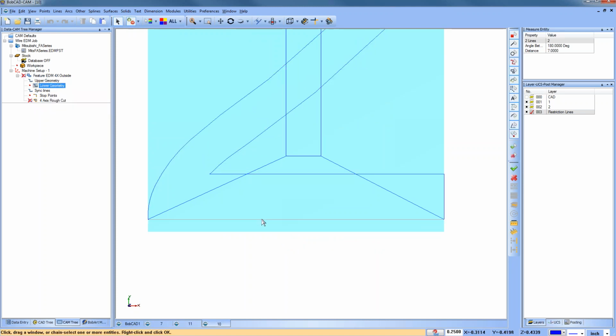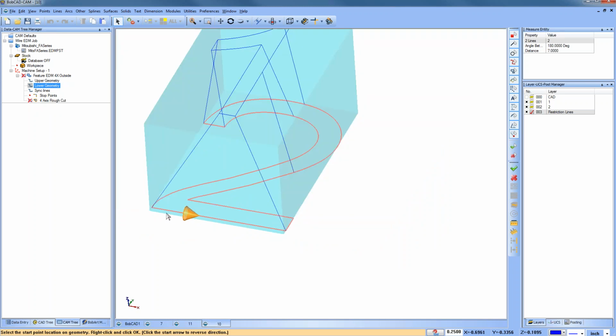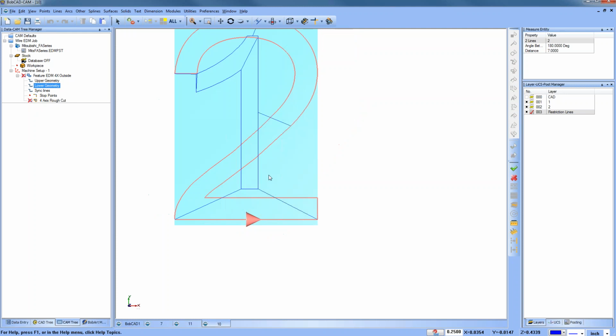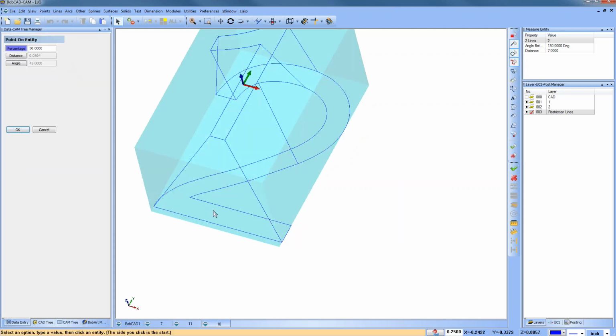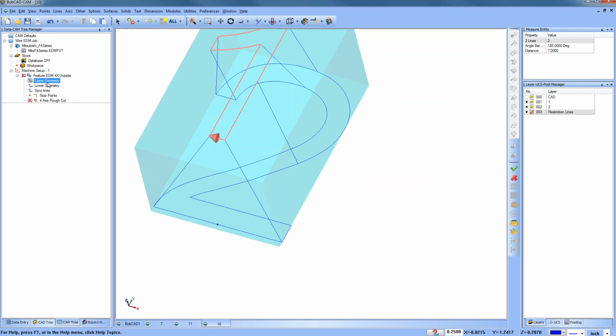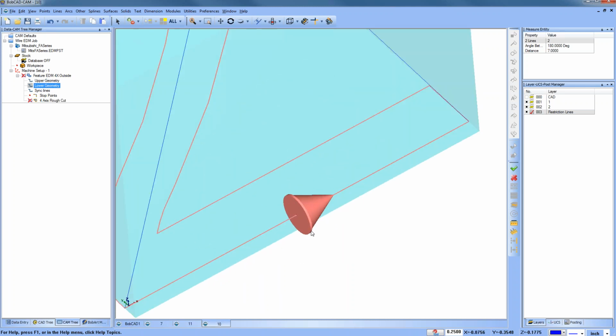So I'm not sure if that is some geometry condition that's causing that one on the lower guide. So I'm not sure. I'll have to find out. Yeah, I mean, you know, looks can be deceiving. Let's do 50% here, 50% there. We go to this one, you can see that one's right on 50, and you can see that one's right on 50. So those are dead on. So it sounds like it may be a geometry based thing.